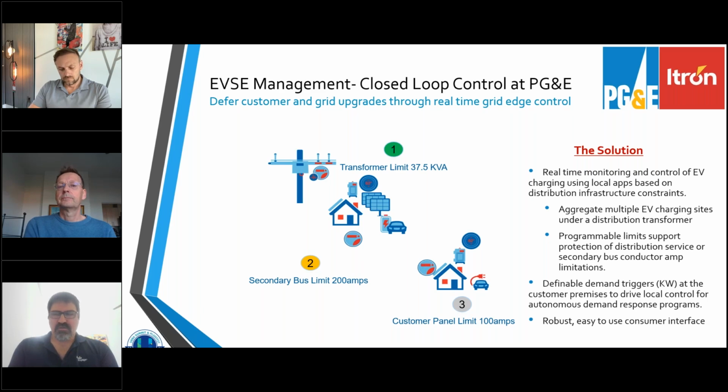One, certainly there's deferred infrastructure requirements for the utility, and it also allows them to pace out the upgrading of their infrastructure. But it also provides an incentive for the customers to want to engage and interact with the utility, because foundationally what we found was that in their particular territory, in many cases they could defer panel upgrades, which were several thousands of dollars. So the incentive for them to share data and be throttled when their coincident peak at the premise level is going to exceed the rating of their panel would save them thousands of dollars. And so this marriage between the consumer and the utility dawned this application where the utility works with the consumer to throttle these EVs in real time to stay within the layers of constraints that you could set in the meter itself.